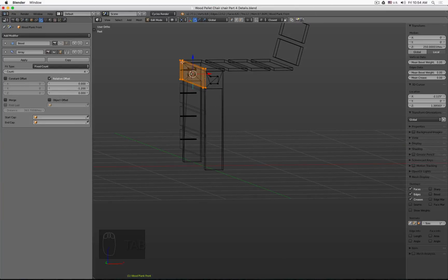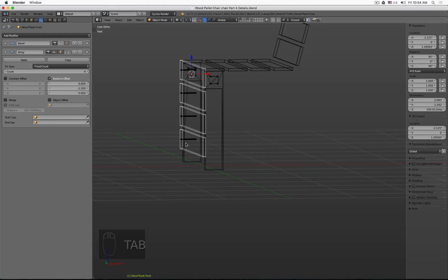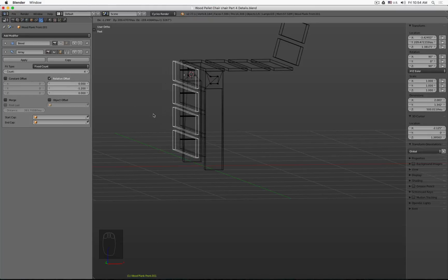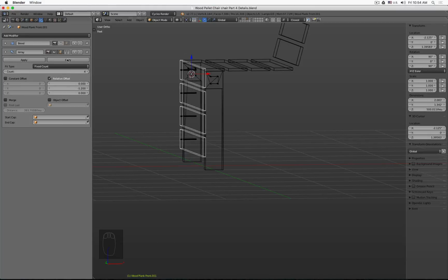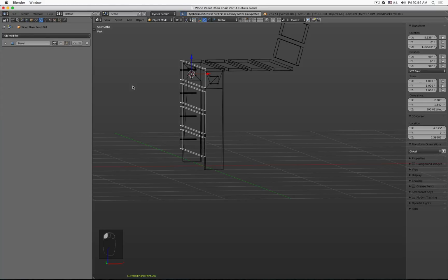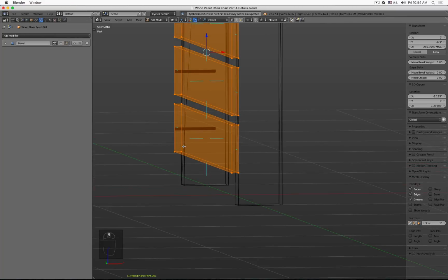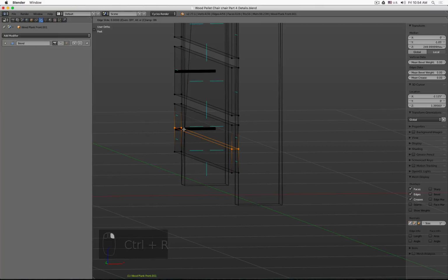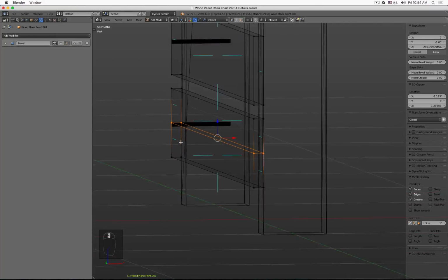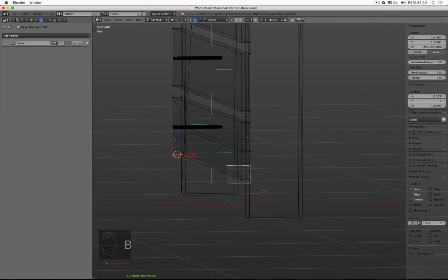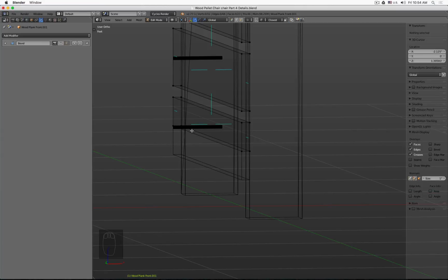If I go into edit mode, I'm back to this part. So there's no mesh I could click. So here's a little trick. Shift D, we make a copy, press escape so we don't move it, and then we apply the array modifier. Then we can go into edit mode. Here we make a loop cut. And for example, the lower part here we can delete.